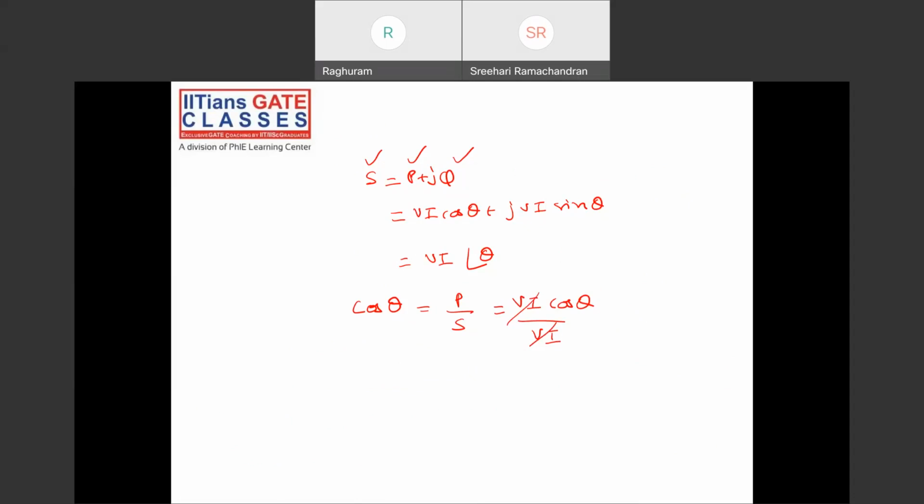Is there any significance of these powers in real time? Actually, there is. The active power is the power for actual work done in any circuit. If it's a resistive network, it is the heat produced in the resistor. If it's a light, it is the lumens output. If it's a motor, the output of the motor is the active power.